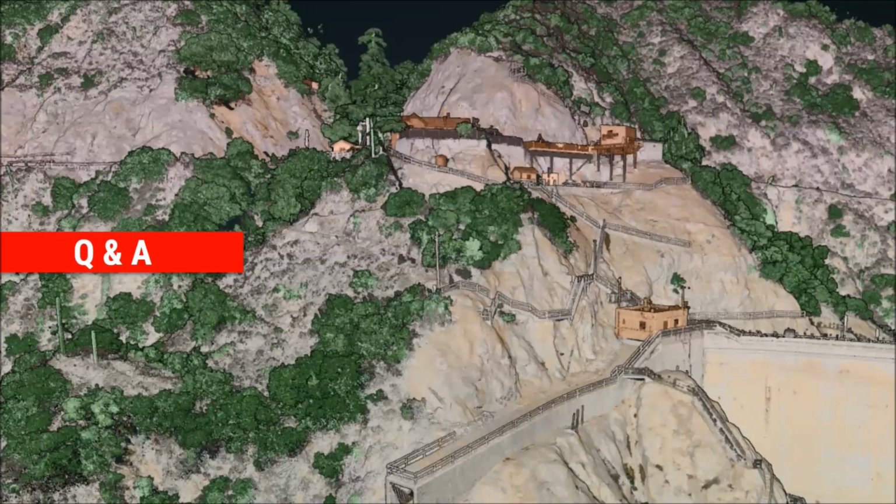If they're not perfectly aligned, there are ways to do alignment using LiDAR snap, things like that in Spatial Explorer. I've also played around with some other software for aligning things. If you do everything right, you fly your figure eights correctly, your flight line's going good, your base station's working correctly, you don't have any hardware malfunctions, then things line up pretty great, and you usually don't need additional alignment. However, if there are some issues, then there are options to make it fit as well.